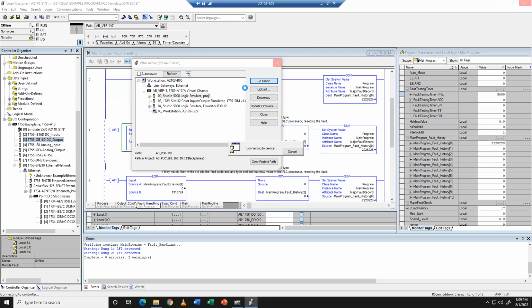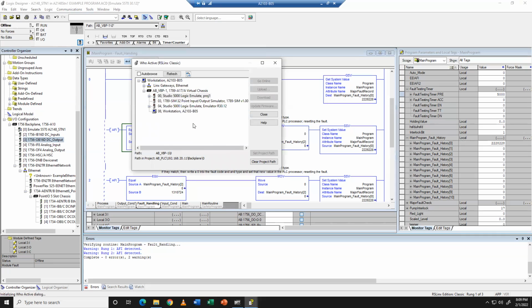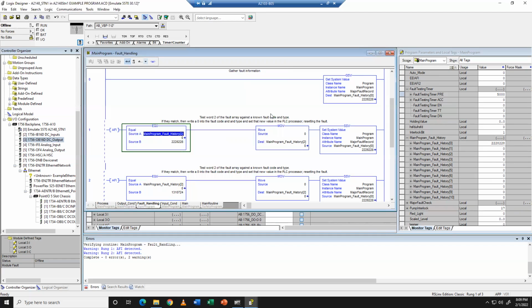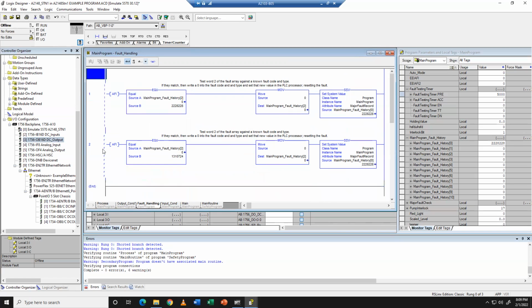If you have an unsigned integer try to write to -1, it can't, it'll fault. So if a programming issue caused the fault, you can sometimes put it into program mode and then back into run mode, and it'll kind of wake up, as long as that programming issue isn't something persistent.